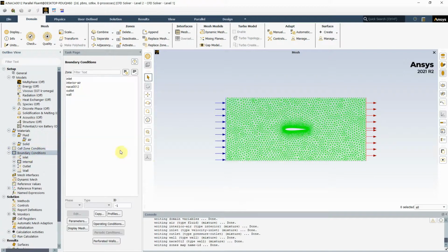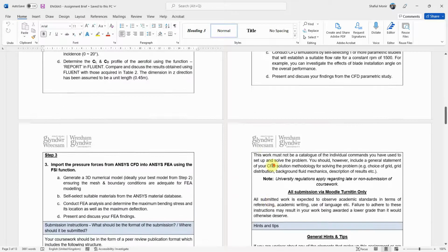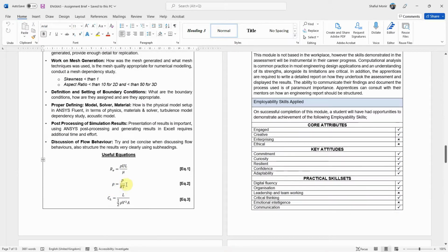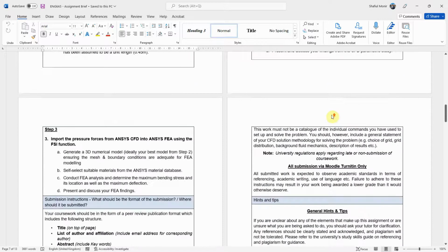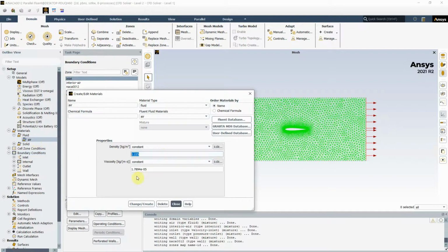And then obviously here what we want to do is go to the boundary conditions, and in the inlet, sorry, I do apologize, the density is not provided because you will have to calculate the density. I provided the equation down here somewhere. Density equals the pressure divided by RT, and the pressure again is all provided. So you will have your own density value and your viscosity value. As I said, remember CFD is only as good as it is compared to experimentation. So you might want to change the density and the viscosity according to the experiment. Okay, so important to change those things. So close.